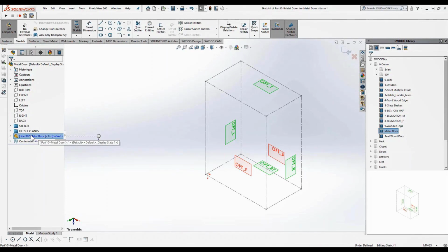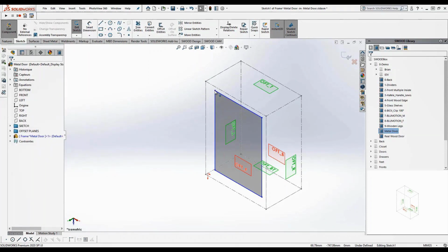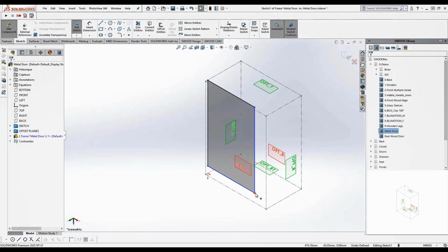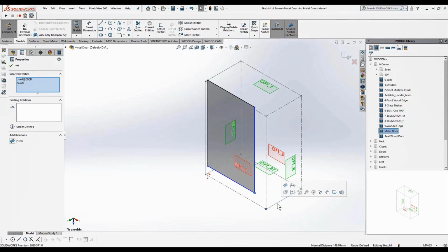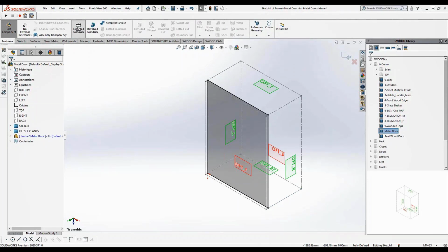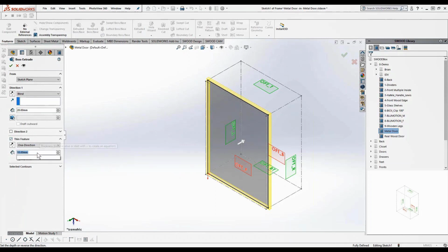So we will start the work just by creating one rectangle. This rectangle can get some constraint with the SWOOD box frame. So here, I will give it some coincidence with different edges of the frame. Now, if you change the dimension of your SWOOD box, you will directly get the dimension of your part changed.